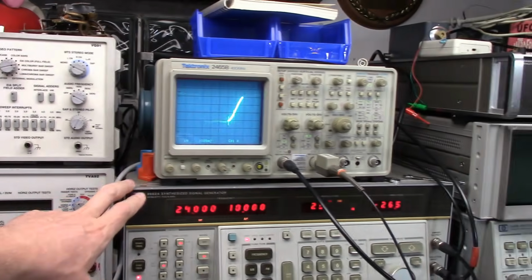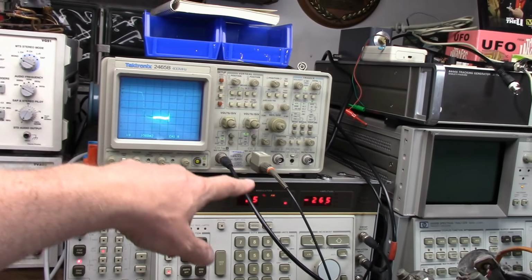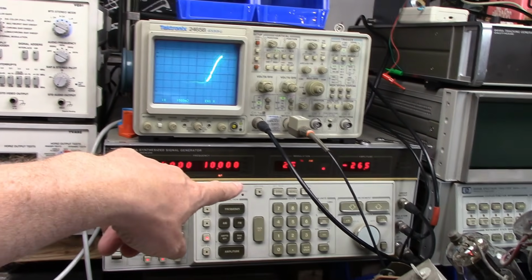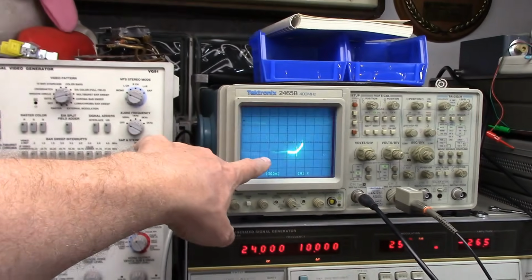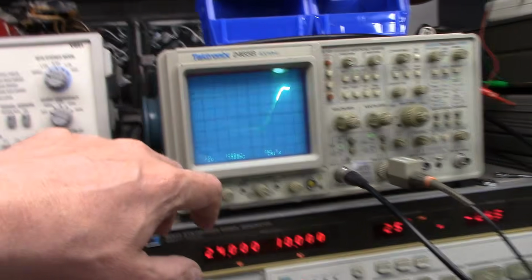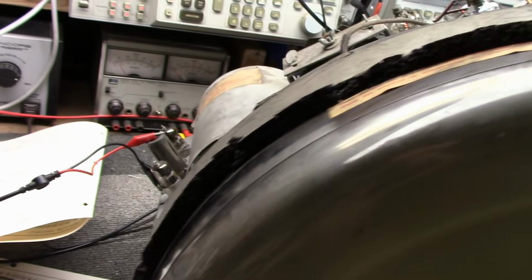Alrighty. And yeah, taking the marker output and using it for the AM modulation input, I got 25% AM mod. We can see the markers on there pretty distinctly. So I think we're pretty well set with the video IF. Now let's tackle the sound, which they show on this side.